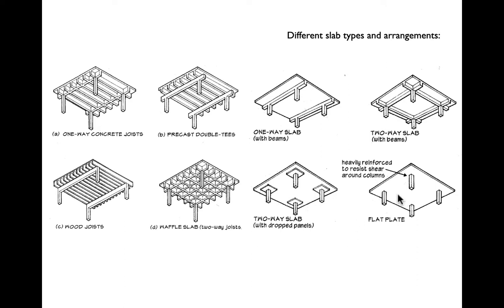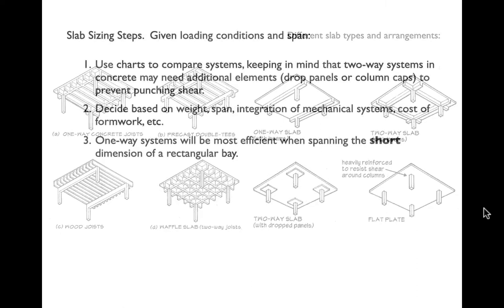We do use flat slabs, but when we do that, we get into heavy enough situations that we have to worry about punching shear, and we're either dropping panels like this, or we are just heavily reinforcing them with a lot of very expensive steel reinforcing.